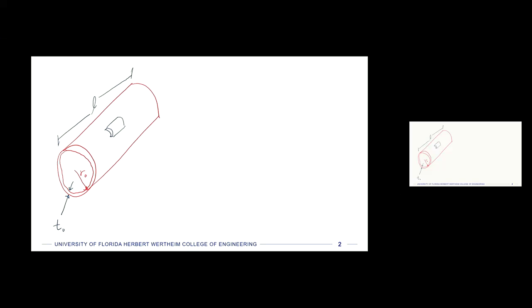So around the circumference of the pressure vessel is going to be our direction number 1, okay? So in 3D space, that's a single axis that goes around the pressure vessel. And we're going to call that direction 1. And correspondingly, that's going to have a stress that goes around. We'll call it sigma 1. Okay, a little bit of a preview there. And then in the longitudinal direction or axial direction along that pressure vessel, it's perpendicular to the first direction. So we'll call that sigma 2.